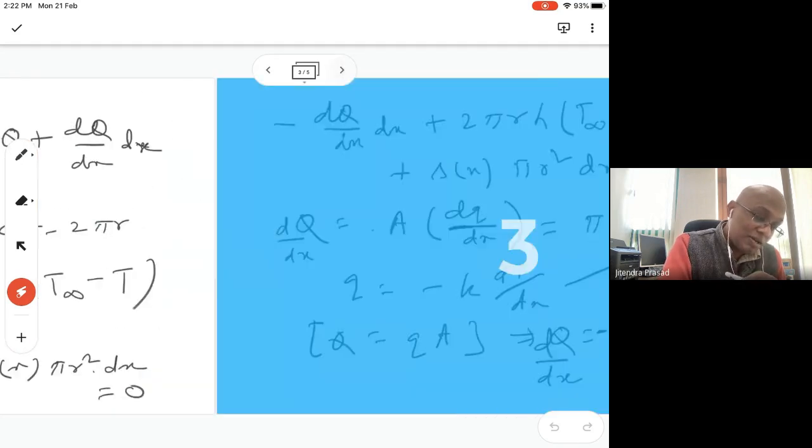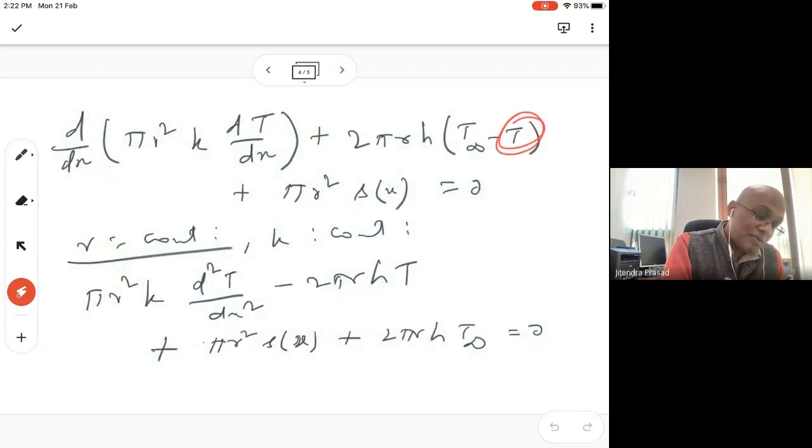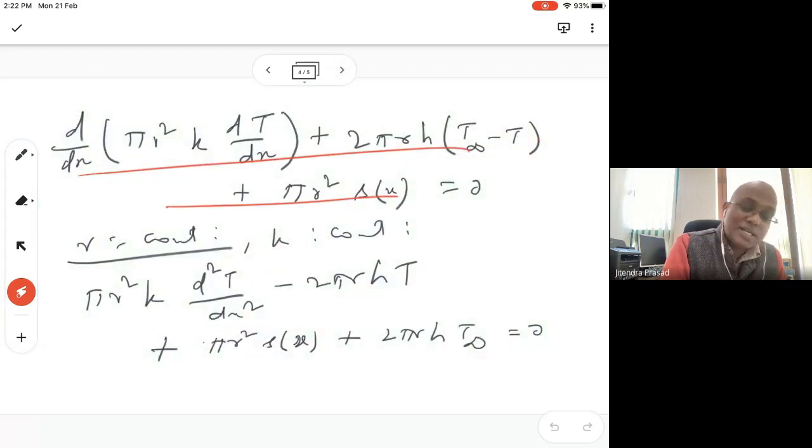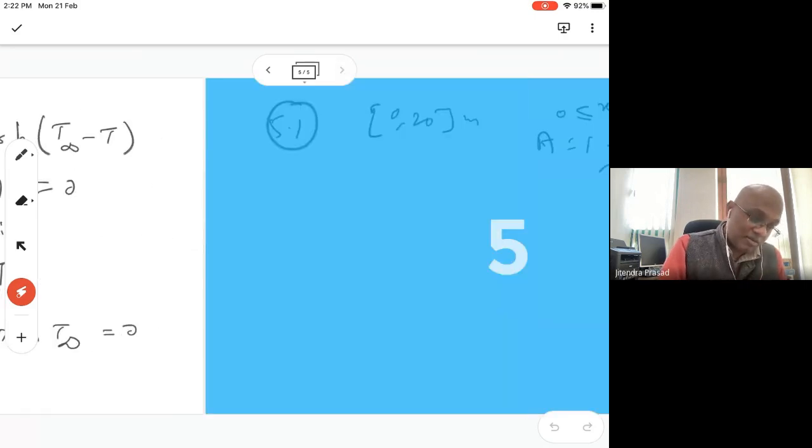and finally, if you derive, then you will see that automatically a T term will appear in the equation itself, which is going to complicate because the stiffness matrix will not only come from this but also come from this component as well. Yeah, so accordingly you have to take care of it.